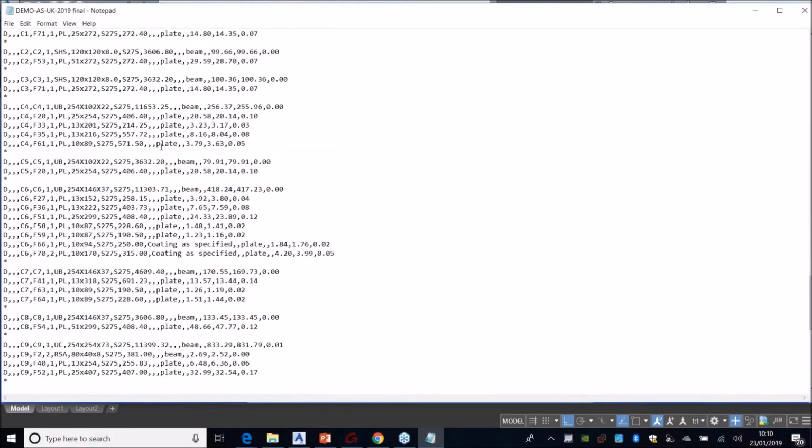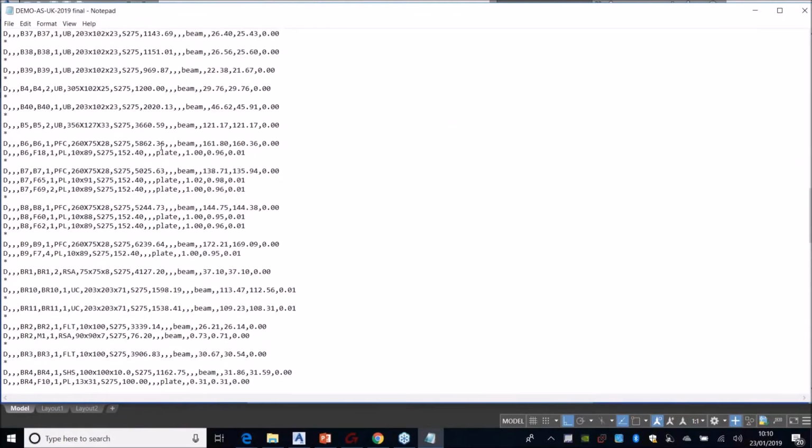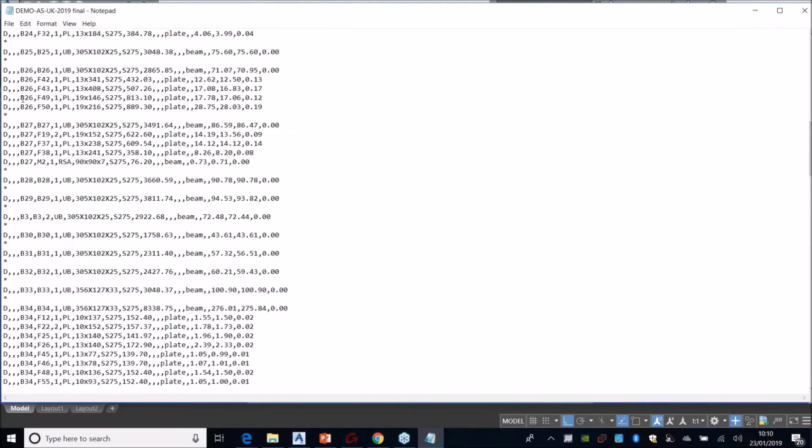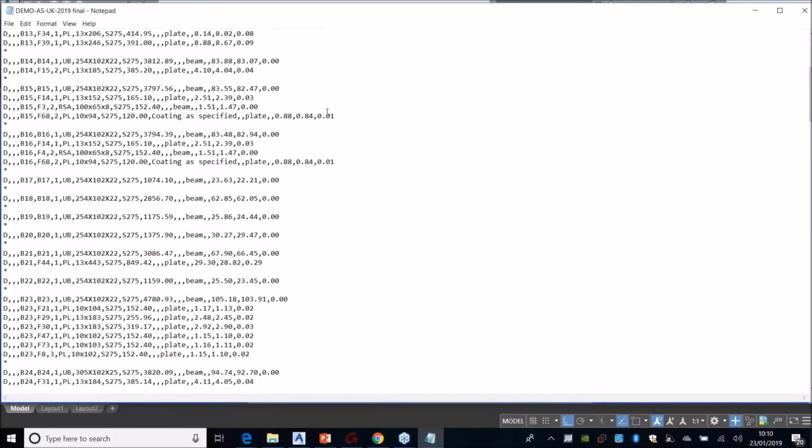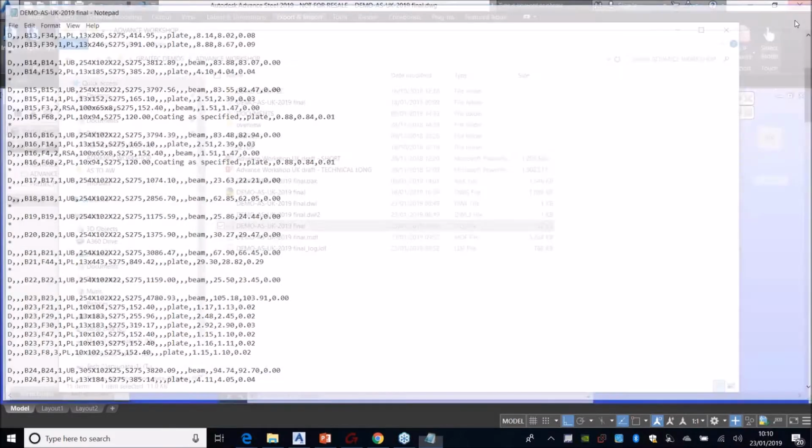Now, the common issue with exporting this type of file to a fabricator is the naming convention or the prefix associated within this format. They might already have predefined prefixes, for example, round bar. This is a common one. So round bar in their system might be just a capital R, maybe it might be RB, and so on. So they might request, hey, due to the fact that this is not populating, we don't want to populate all the entries manually. How can you adjust this so that we can receive the information seamlessly?